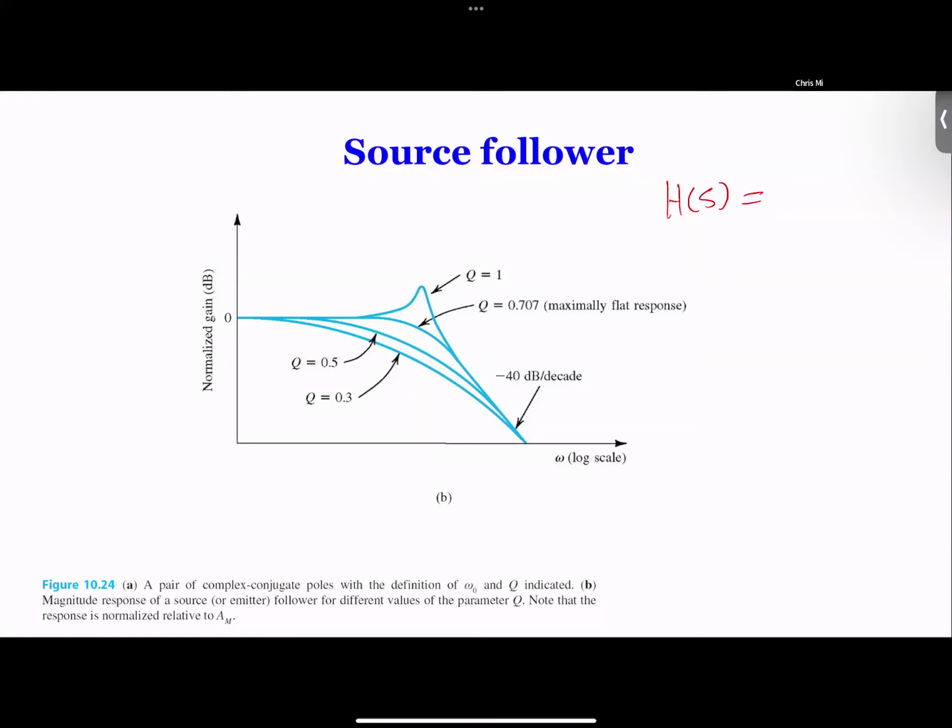for example, this one here, the smooth one, is where you have 2 real poles. And this one, you have solid 2 real poles. And this has 2 equal poles. And the other one, you have 2 complex poles, and this line becomes like going that way. You might see this in control theory, and this becomes some sort of resonance. It could go really high, your Q is very high. Also, another thing you notice is that because you have 2 poles, this line is going to be a 40 dB instead of 20 dB drop per decade.